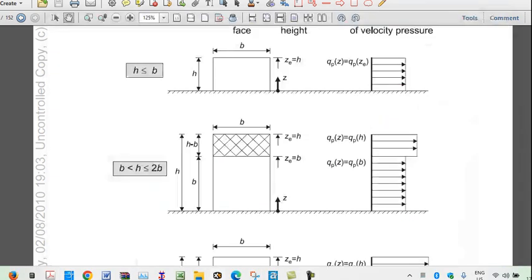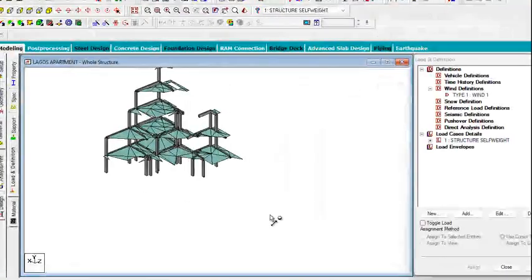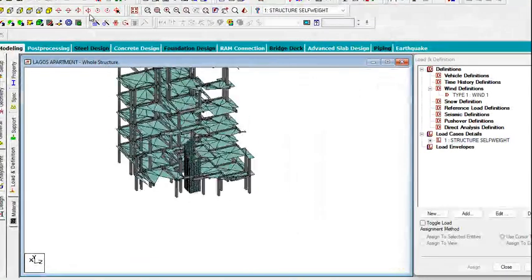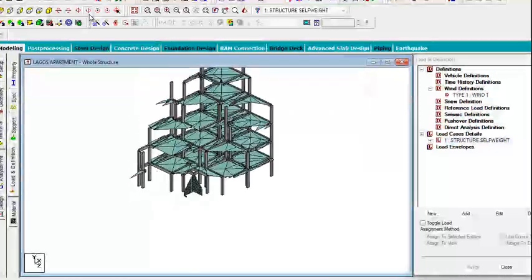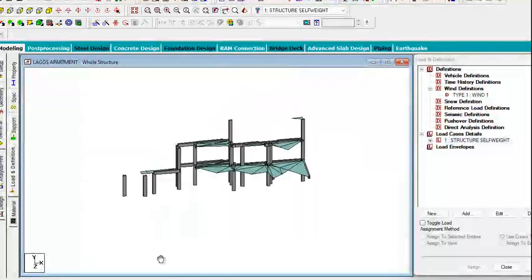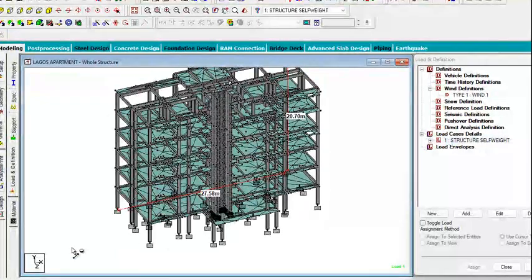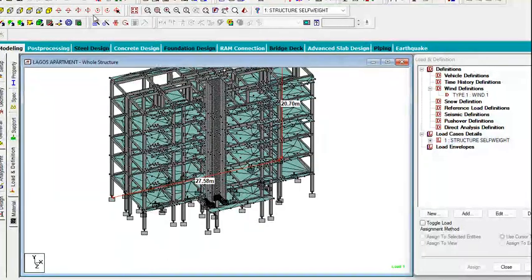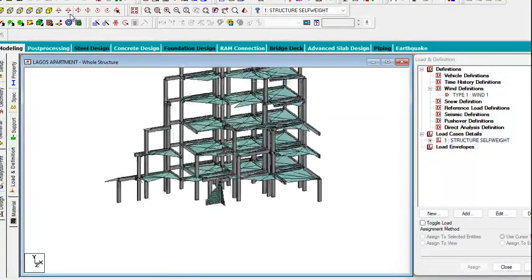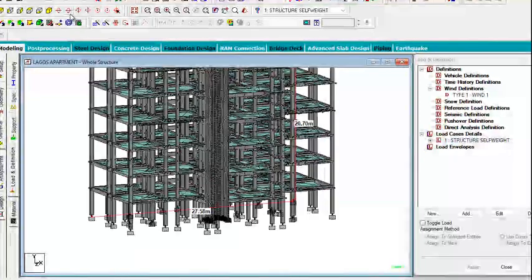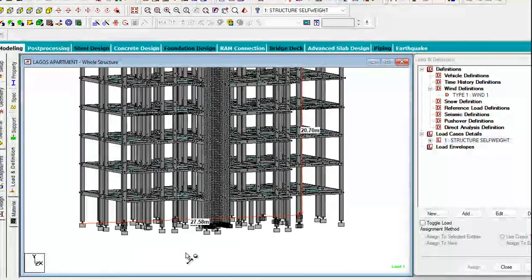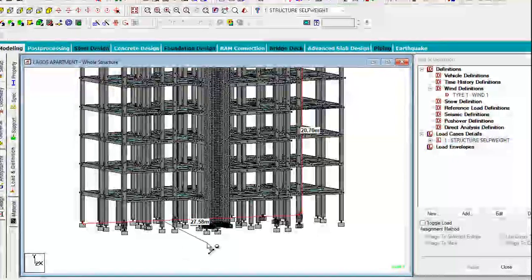Now, this applies to wind in this direction. Okay, so 90-degree wind is applicable to this building in this direction. Let's see how that impacts. If you're applying the wind load in this direction, we look at the building dimension in that direction, the crosswind dimension.